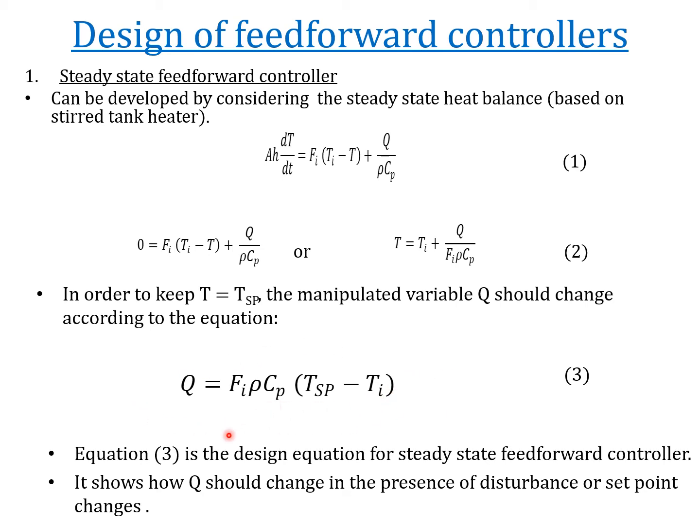Okay, and so this equation is the design equation for the steady state feedforward controller, and it shows how the Q should be changing when there are disturbances in the system. Which in this case will be the temperature changes.